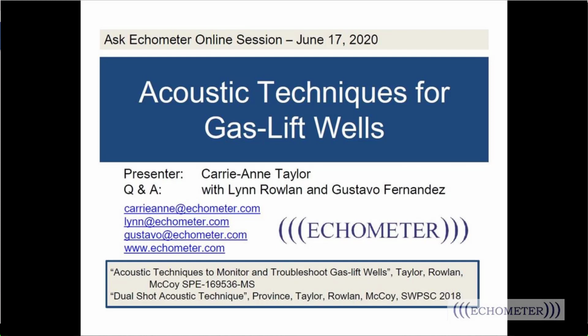If you have a liner at 8,000 foot in your well, and you got to shoot down to 10,000 feet, then you got to use more pressure to get past the liner, because the liner removes some of the energy from the traveling wave. So it's complicated. It's best to just have experience for your wells and learn how much charge pressure gives you the best results.